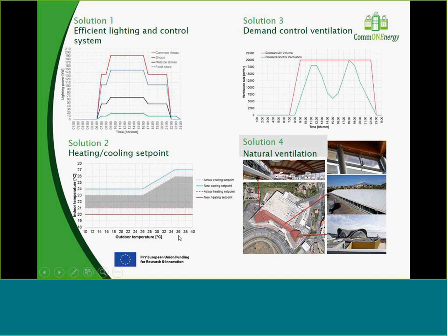Second solution, we changed the heating and cooling set points. Before, the heating set point was a constant 21 degrees, and the cooling set point was 23 Celsius, when the temperature was around 26 Celsius outside.